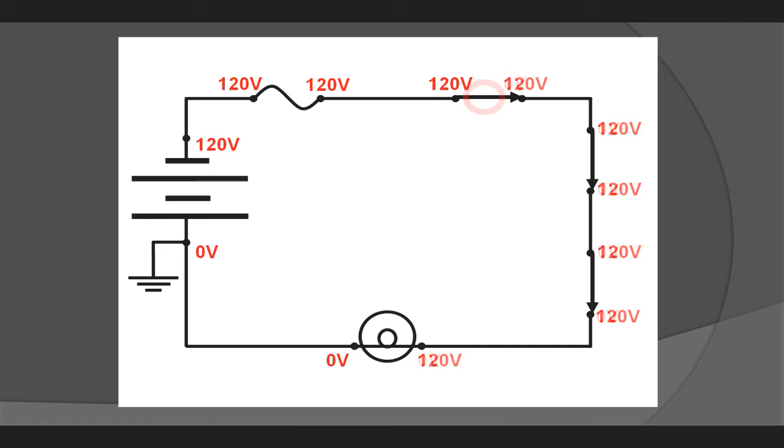How about now? Though this may seem strange at first, this is probably the most common open fault, a simple blown bulb. This is important to know. Taken from the readings alone, a blown bulb looks just like a functioning circuit. The only difference is there's no light. Here's one more. Can you see where the open is? In this example, the open is in the neutral line between the bulb and the positive terminal on the battery. As we stated before, even though 120 volts is present on the lamp, it cannot energize without completing a path for current.